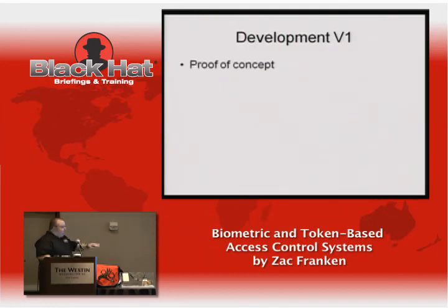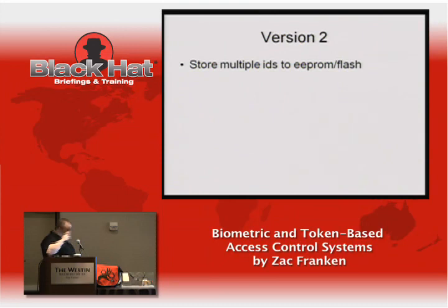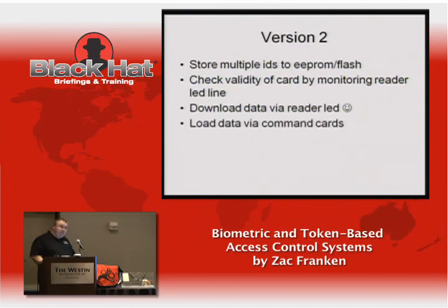So what you're seeing here demoed is the proof of concept version 1. It's got a very basic feature set. We can record, we can replay, we can disable, and we can enable. Version 2, slightly brighter. It can store multiple IDs in Flash. It checks, which this proof of concept doesn't, the validity of the card by monitoring the reader LED lines. It can download via the reader LED. And it can load data via command cards.